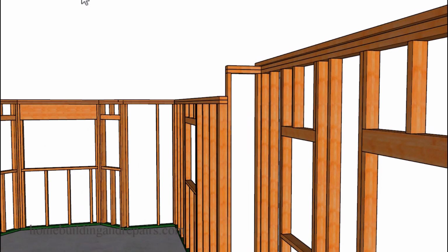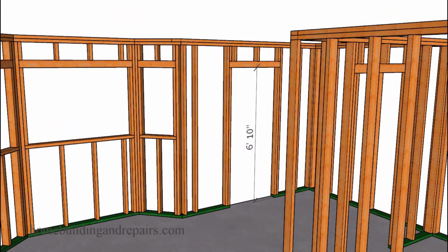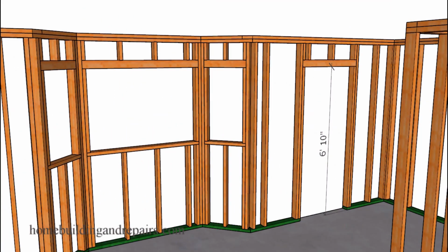because windows can usually be installed a little wider and longer. And I'm not about to suggest that you cannot install a window at a different height or create a bunch of crazy different patterns. And for those of you looking for that measurement, it is usually going to be 6 foot 10 inches, because most doors are about 6 foot 8 inches. However, you would need to check with your manufacturer to verify that information. And I'd be willing to guess that this measurement probably applies to more than 80% of the homes built, and probably 90% of the homes that I worked on.